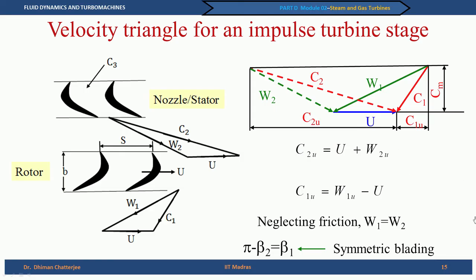But for the way we have denoted it, the blade angle is denoted by the angle between the positive direction of W and, for example, the negative direction of u, which is this angle. So, this angle is my beta, which means the vertically opposite angle also should be my beta. So, this should be my beta 2.